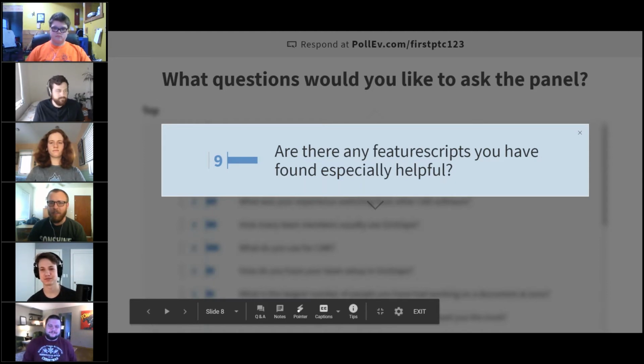And then also, I think through Julia, we heard about this vent feature script, which is essentially a slicker version of the Lighten feature script that we have been using, and it's much less process intensive. So those regen times drop down really significantly when you're doing similar things with the Lighten versus the vent feature script. So finding ways to not only do the things that we need to do with Onshape, but also be more resource efficient, I think both those feature scripts are going to prove really useful in upcoming seasons.